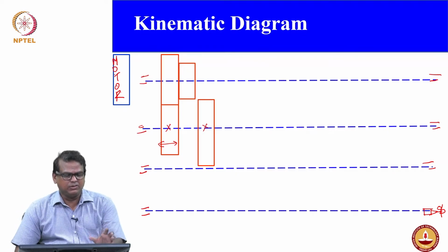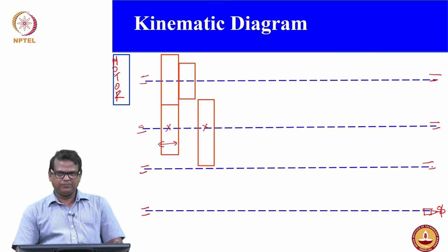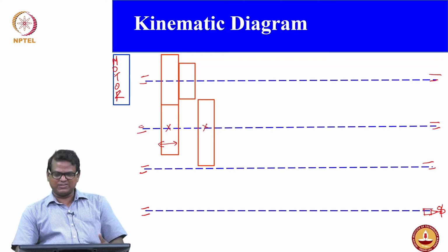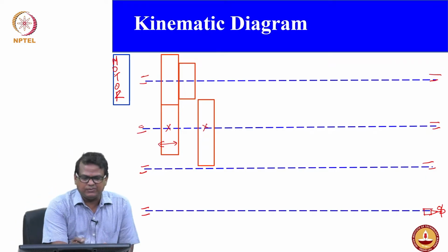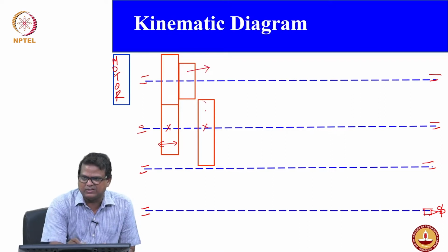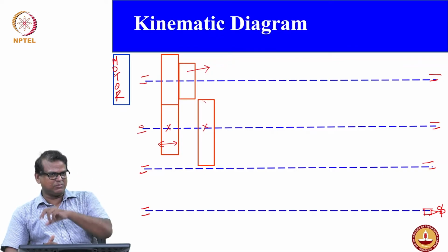Now, on the current mesh, what is the speed you would expect? 500 rpm, because of bigger size to smaller size. The moment you shift this one, these two engage. When these two engage, what happens to the speed? It will be 355, because it is smaller gear to bigger gear, so the transmission changes.